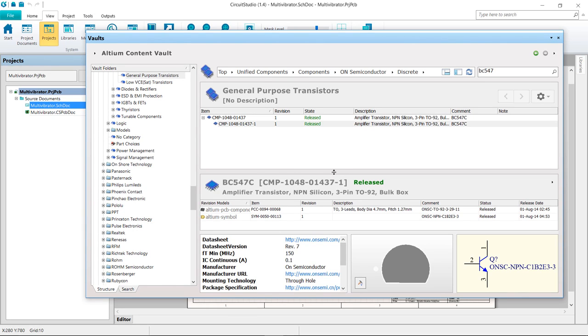When you're in any editing or placement mode, a command crosshair cursor is active. Moving the cursor to the edge of the document window will automatically pan the document. If you accidentally pan too far while you're wiring up the circuit, just press Control Page Down to redraw the schematic window, showing all placed objects. This can be done even if you're in the middle of placing an object. It's good to be familiar with the hotkeys.